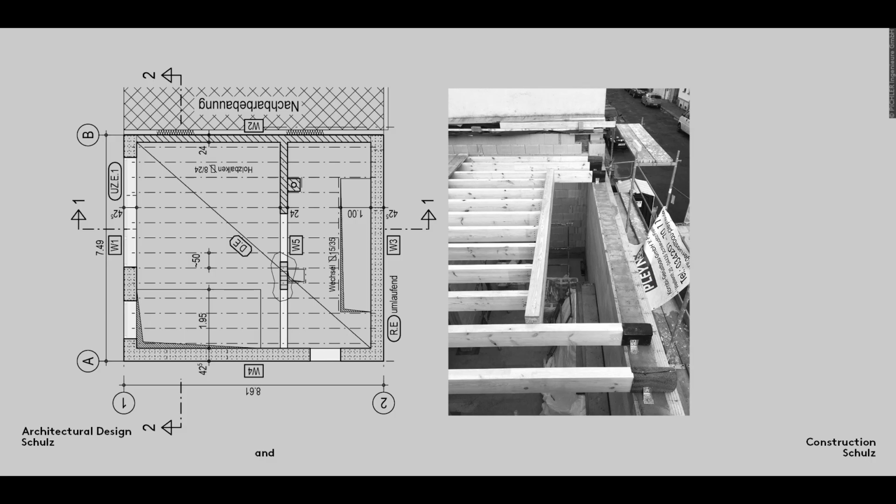Here in the Hauenstein house, the stairs were placed at right angles to the span direction of the floor. The consequences are clear to see. The trimmer joist along the floor opening is taller and wider than the other floor joists because it has to absorb the load from the other 8 trimmed or bridging joists. The resulting design problem is solved by setting the underside of the joist at the same height as the other joists and concealing the projecting joist in the floor structure above.